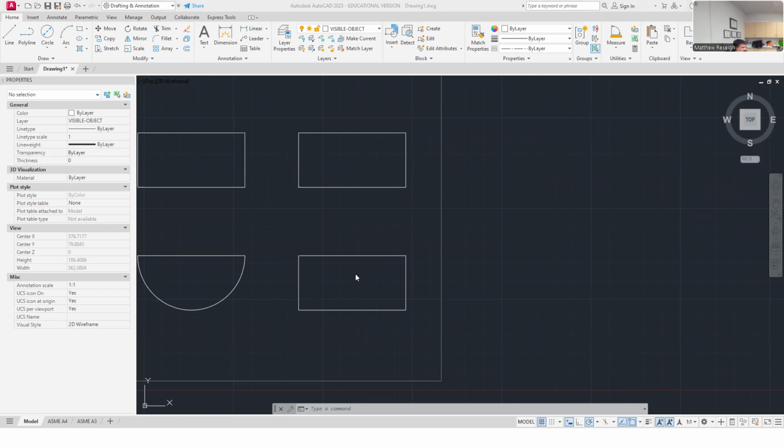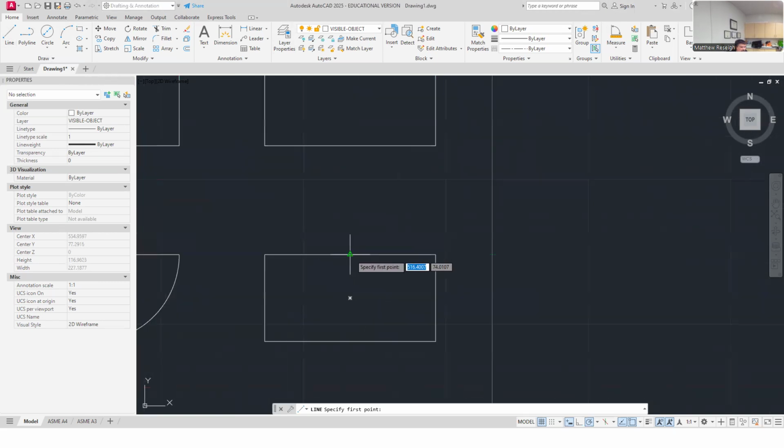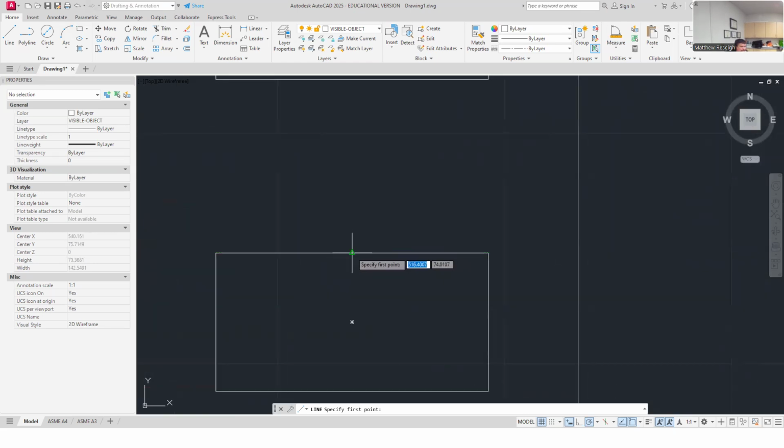This is a T slot. It's kind of like the dovetail, but maybe a little bit easier. I'll draw it from the front view, from center out. The first T is 10 overall across, but if I'm drawing it from the center, I might cursor over just 5, and then I'm going to come down and say that this depth is 8. I'm just following the dimensions on my drawing.